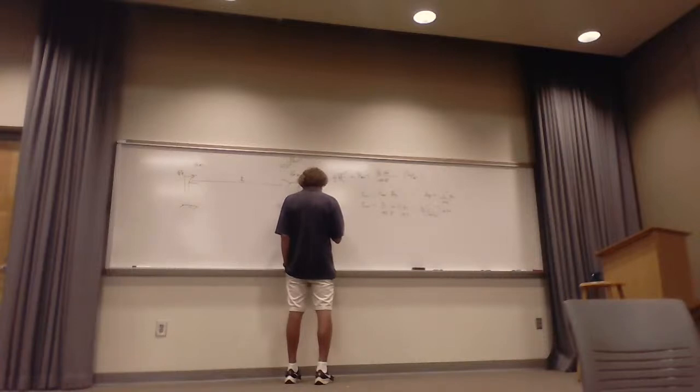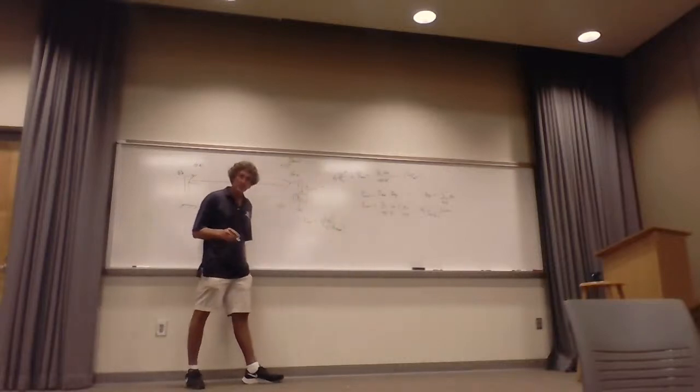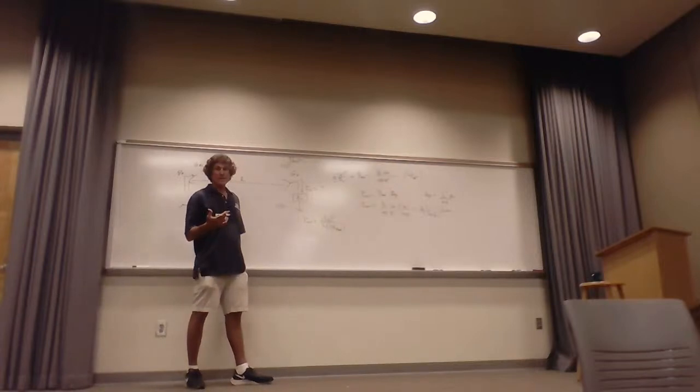It was 1/2 times I squared. I mean, now actually we used V, didn't we? V OC, right? We do it with V OC, squared divided by the resistance, which was 2R antenna or 2 R rad, right? Remember that? Why 2 R rad? Because you've got the radiation resistance of the antenna and the load resistance is assumed to have an identical value. And the imaginary components go away because you're going to have a conjugate for the load impedance.